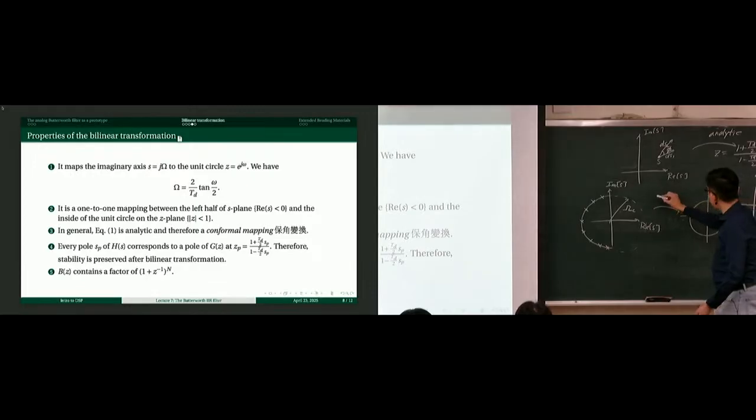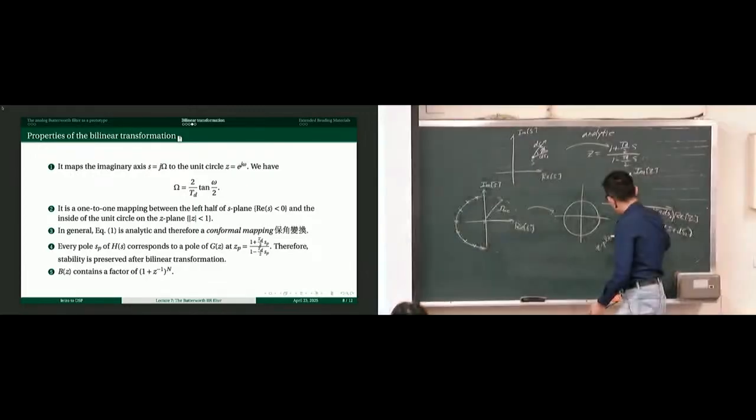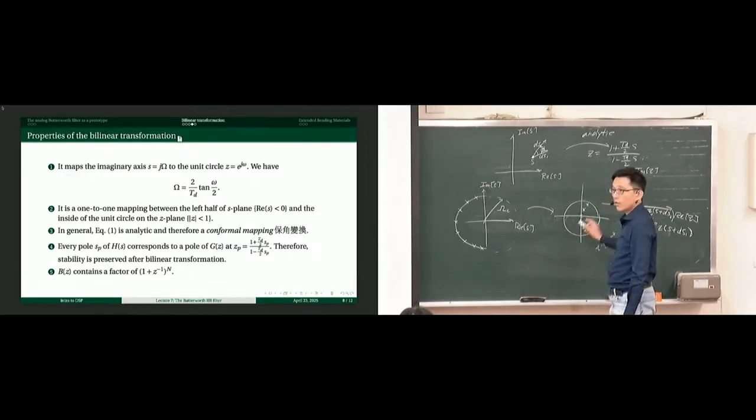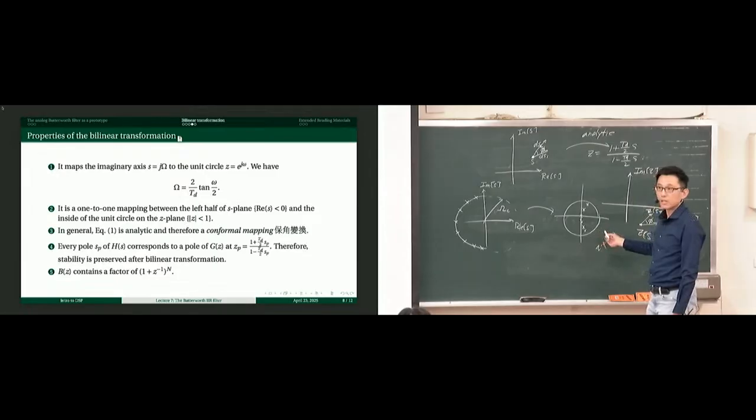Okay, so now from S to Z, this is the Z plane. Now these poles, wherever they are, are going to be inside the unit circle. Might be something like that. We have equally many poles now in the Z domain, but all of them are guaranteed to be inside the unit circle. And isn't that great? It is great, right? Make the response great again, right?